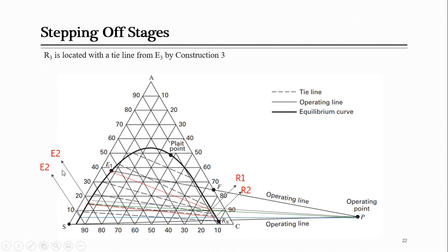But in the case we were looking at in the video, P was located on the extract side. So when you join P and R, like R1, R2 or anything else, they will definitely pass through this line on the extract side. They will be cutting the line, and that will be your extract point.